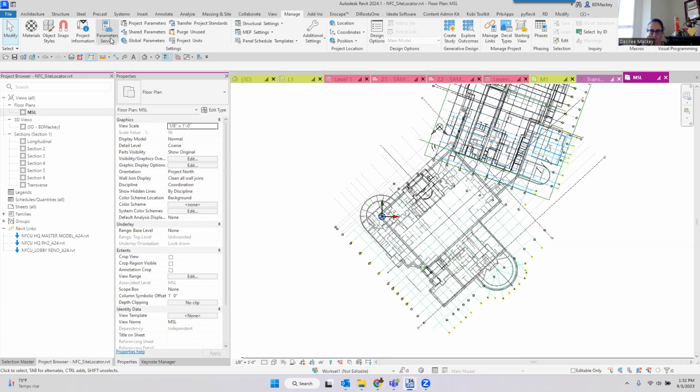Then you can choose certain ones of those parameters and break them out into sub files. So they're still in the master file. The master file still controls it, but you can group them out into separate groups and then give different users rights to those parameters. Where I'm thinking this is going to be great, like in an MEP world, I can have the company master shared parameter file. It's one file in the cloud, but then I can have electrical ones grouped out, or maybe just electrical lighting grouped out versus electrical power, or whatever you want to do.